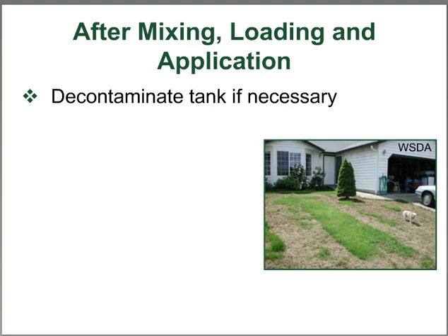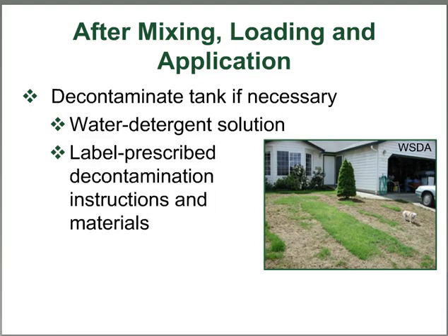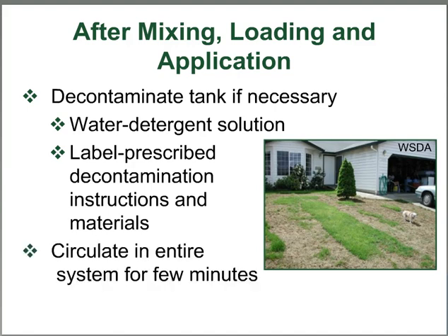As a basic rule, you can simply use a water detergent solution or use the label prescribed decontamination materials and circulate them through the entire system for 3 to 5 minutes. Afterwards, flush the entire system twice with clean water. Also clean nozzles and screens.